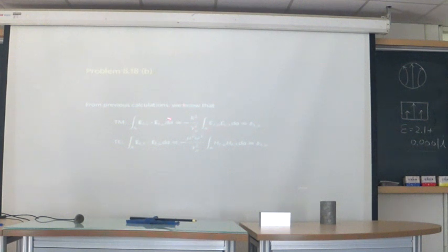From the previous work, we know that for TM modes and TE modes, the integration will finally equal the Ez integrations. So if you want unit normalization, we need to make our Ez fields equal to these two constants. Okay, finished.